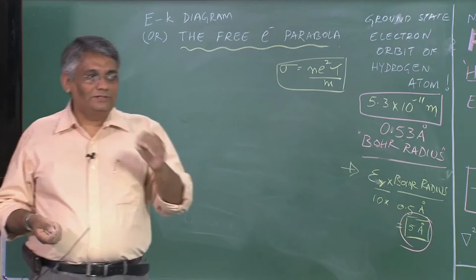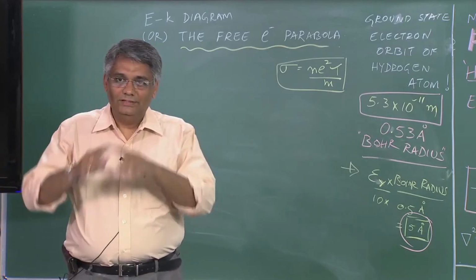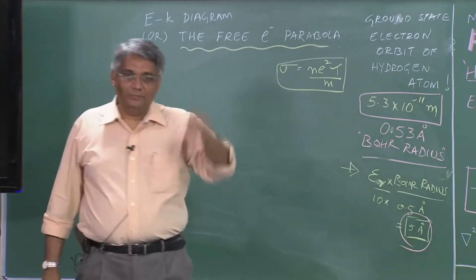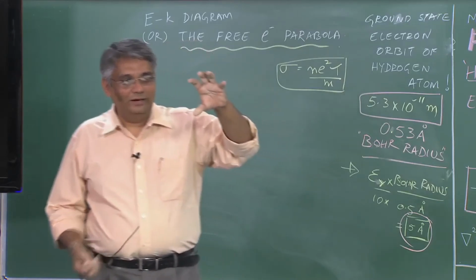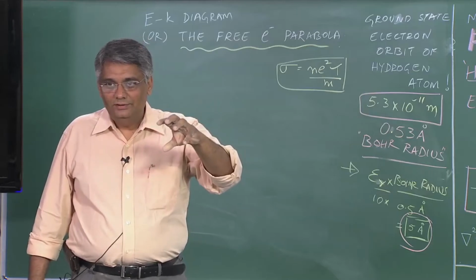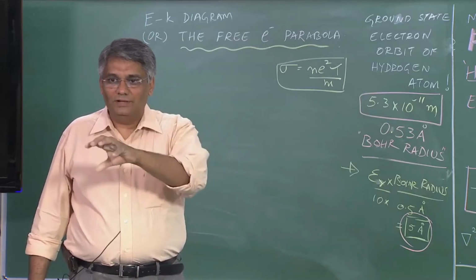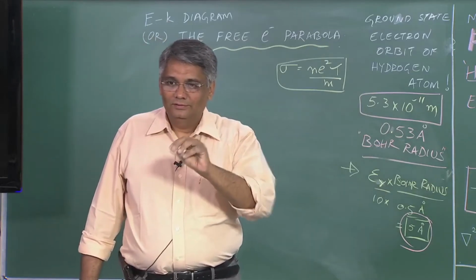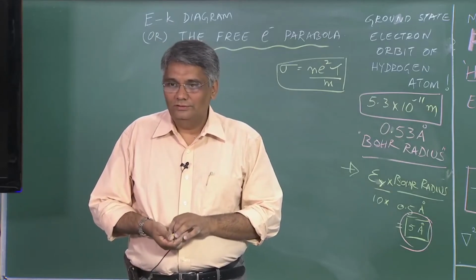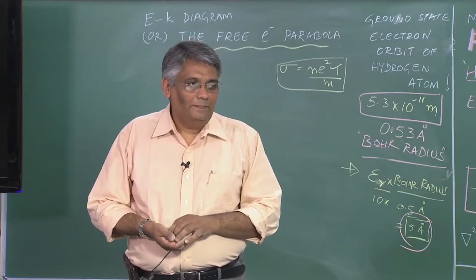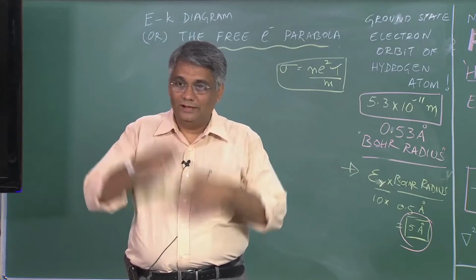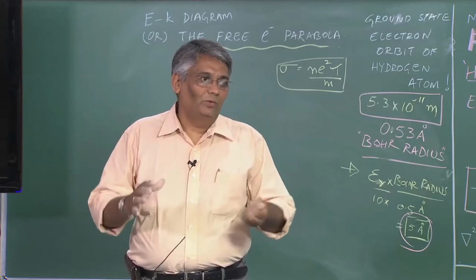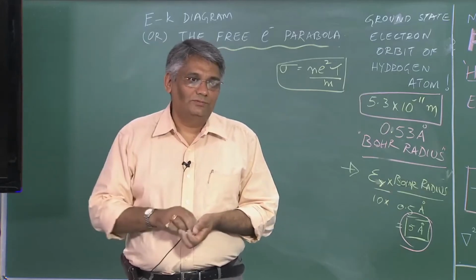The electron in a semiconductor is free to propagate only within that particular radius, not beyond that. Now I have a well-defined radius which comes from the Bohr radius times the dielectric constant or relative permittivity, and if this value is say 5 angstroms, I can calculate the 3-dimensional volume in which the electron is free to propagate.